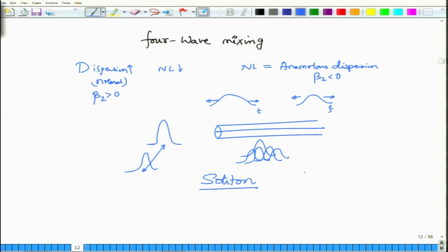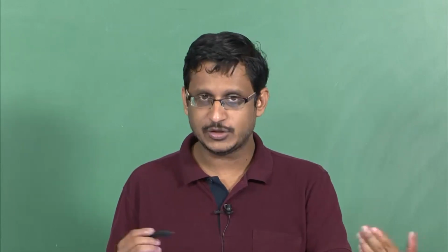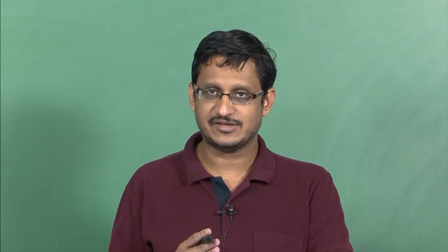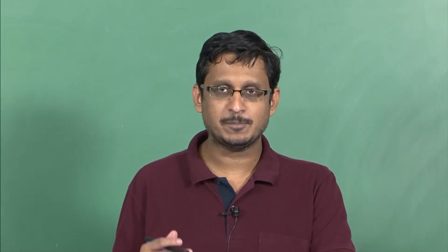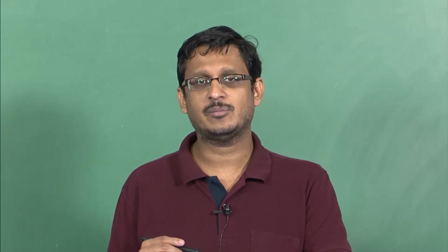This was actually discovered way back in the 70s. However, experimental support did not turn up until about the 80s, and by the late 80s everyone was predicting that solitons would be the next big thing in fiber optic communication systems. Unfortunately that did not happen, for a variety of reasons. One of the reasons is that solitons require that the fibers be essentially lossless and that dispersion and nonlinearity be exactly balanced out, and if there is any perturbation in one of the parameters, as would happen in a real fiber, then these pulses would lose their soliton nature, and they will behave like any other pulse.